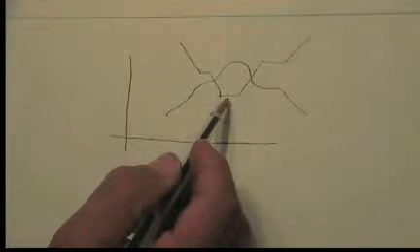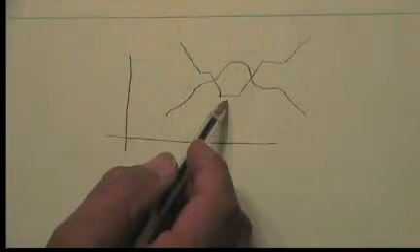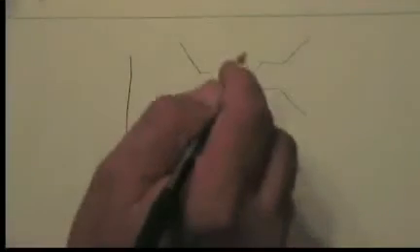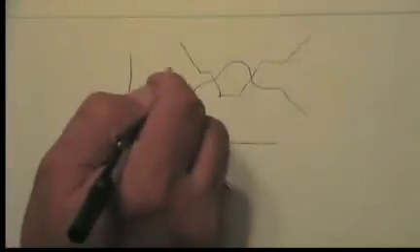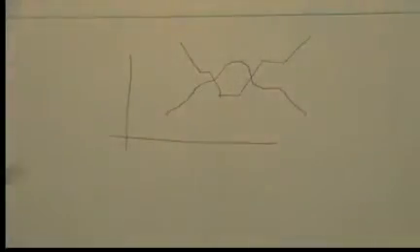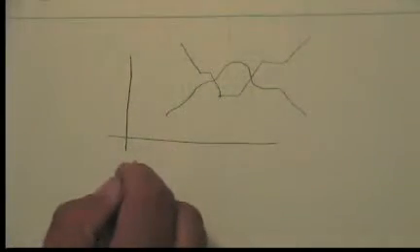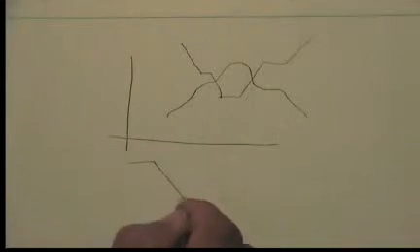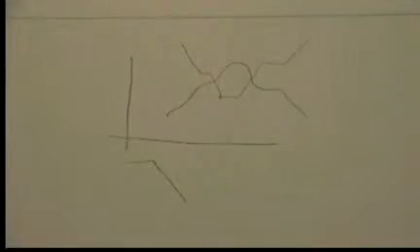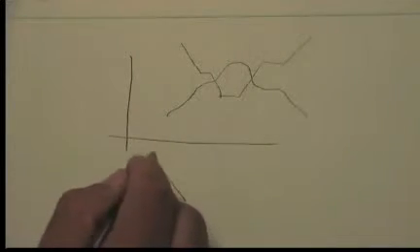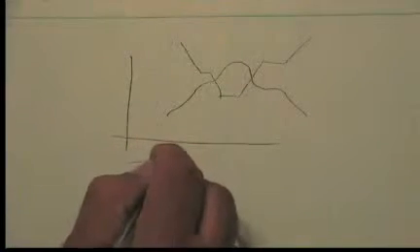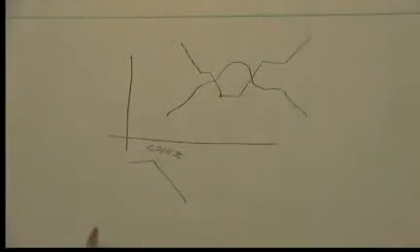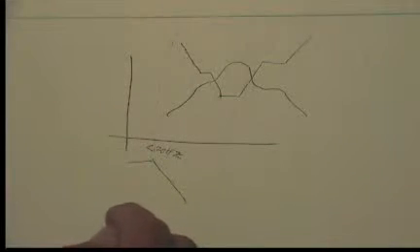Now, to achieve this, I'm going to cascade a bunch of parts together. So first of all, let's start from some point at really low frequency, anything below 20 hertz. Sorry, well, we can't hear that anyhow. I'm going to say the first stage is going to be just a low-pass filter that has a response like that, whose frequency is below 20 hertz, something like that. So that's my first stage.